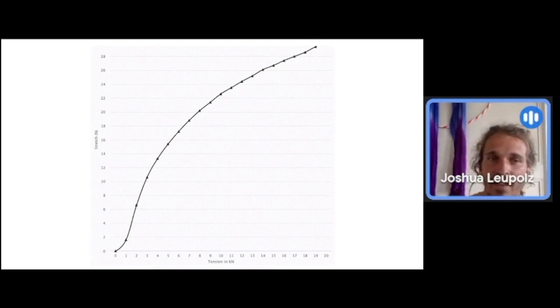But as you can see, a leash fall is not super slow. Within 1 or 2 seconds, the line is loaded. And then you need to use this other value, which I measured at 2.2% stretch. You would get a huge difference in forces on your leash and on your body. And that's, I think, pretty important to know, and that's why we need better values.